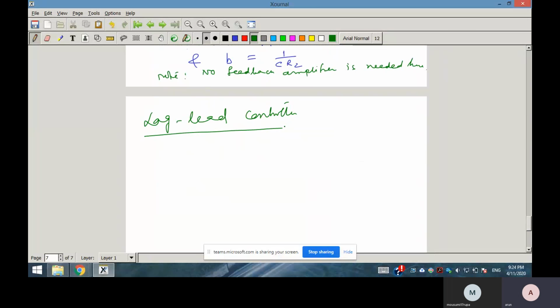So we saw that the ultimate objective is to obtain a certain phase margin and gain crossover frequency using lead and lag controllers, because the steady state error specification will be met by the servo gain K, as we said. So using the normalized part of the controller, that we are considering as H(s), we want to obtain only two specifications, that is phase margin and gain crossover frequency.